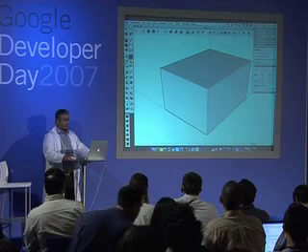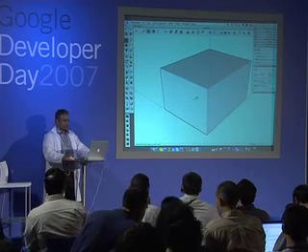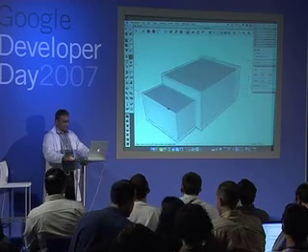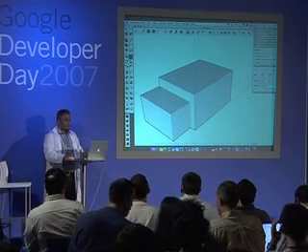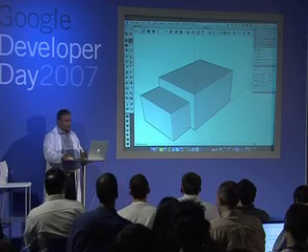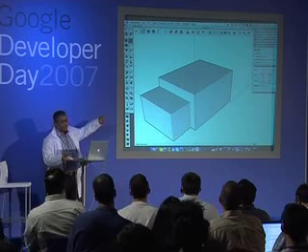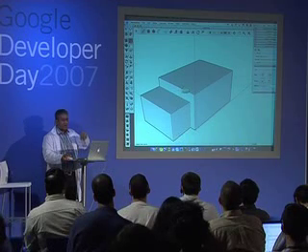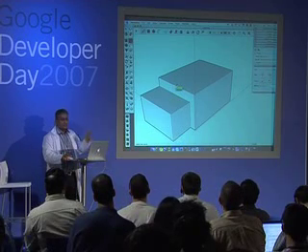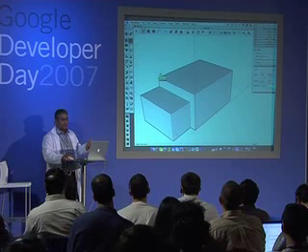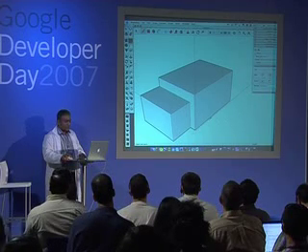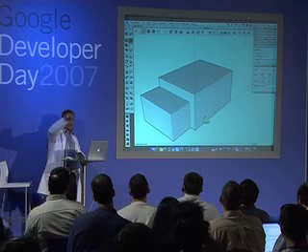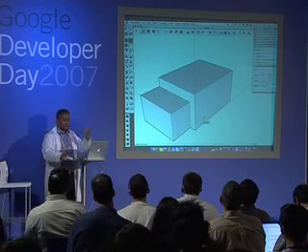I want a garage on the side. So I'll draw a garage. I'll make it about that big. I want to put a roof. Okay, so as you notice the red dot, that is selected a line. Blue dot, midpoint, endpoint. If I wanted to draw something parallel to something else, all I do is pick a point, say parallel to this, and just draw the line, and you'll see that.